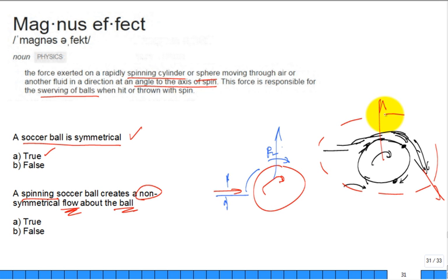Yes? On a tennis ball, you know how there's that white line that kind of traces around it? Is that for a reason as well? I don't know. The same with the baseball, the little stitching lines. Yes, but they can exploit those. There's videos of how they actually exploit it, where on one side they won't have that bump from that stitching, and the other side it does. And if they can get it to spin that way, it's more smooth on this one side and rougher on the other. It's the same point of delaying or changing separation points, and it can make it curve like that because of the smoothness on one side and the roughness due to a stitch on the other.